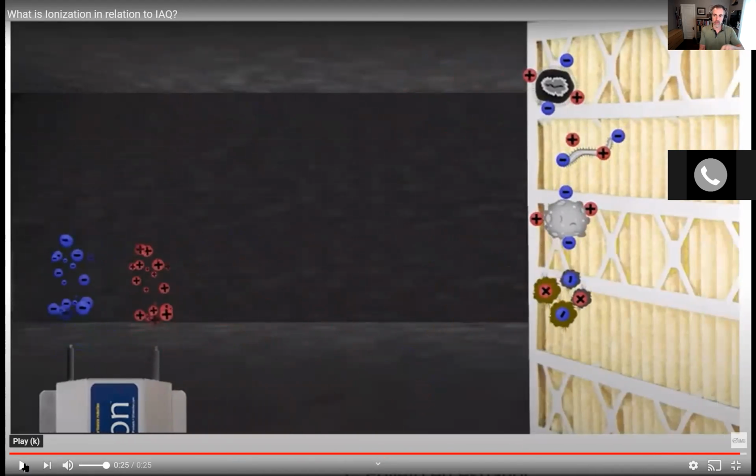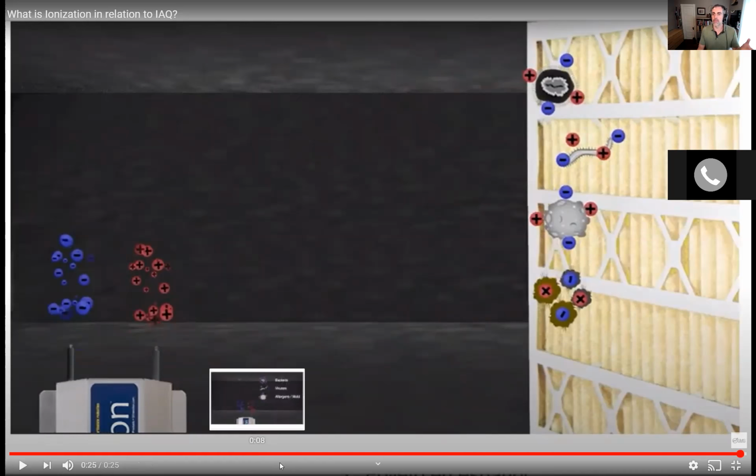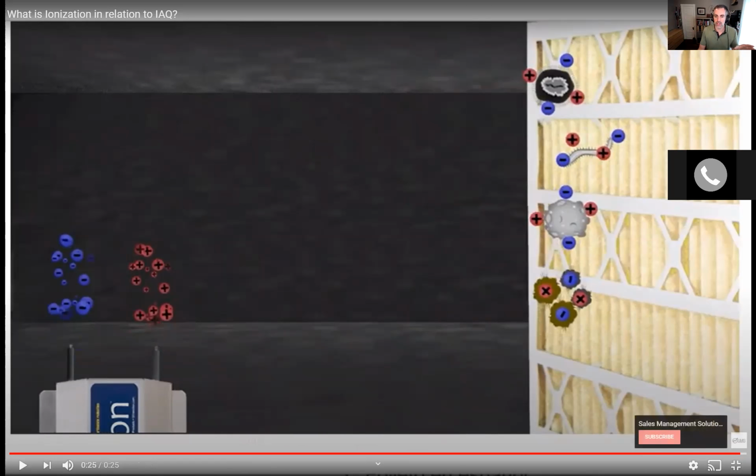So back to your point on my last video, what we're doing with PCO and UVC lamps is obviously the most important because of killing bacteria and airborne viruses. But this is also a huge benefit because, as you guys know, everything starts at the filter and then everything comes after that. We have MERV 11 and MERV 13 class filters, but whether you're using ours or anybody else's, if there's a way to improve a filter's ability to catch even more particulates before it gets to the coil, where a lot of contamination happens, then great, let's improve that. That's one of the biggest benefits and selling points of ionization.